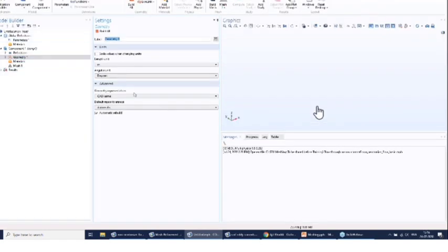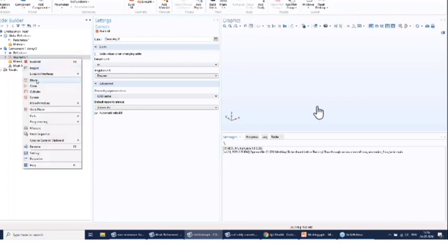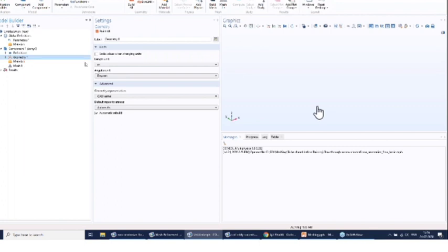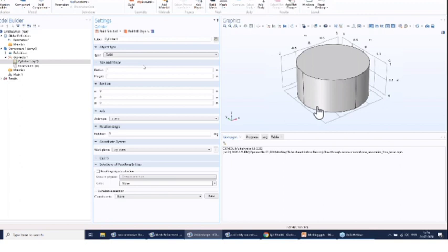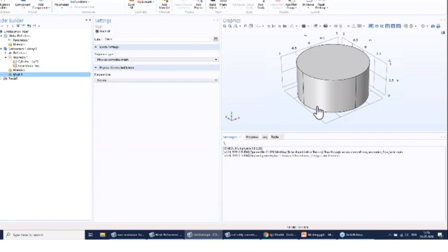And now I'm moving to my COMSOL GUI. I hope you are familiar with the whole GUI here. You might have worked with some problems in geometry in the last session and so on. So I'm going to create a cylinder. Now, after you have created your geometry, next I will mesh it. Once I go to mesh, there is a sequence type which is physics-controlled, and you also have the option of a user-controlled sequence. I will come to what the difference between these two is, but let me just go with physics control.